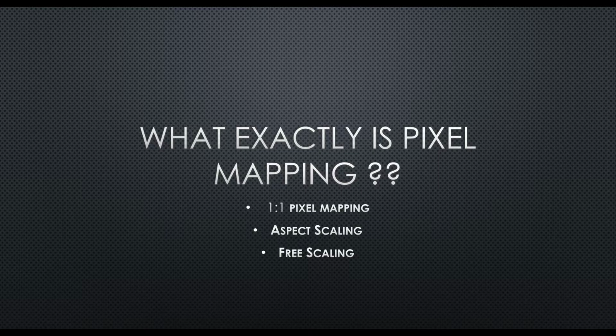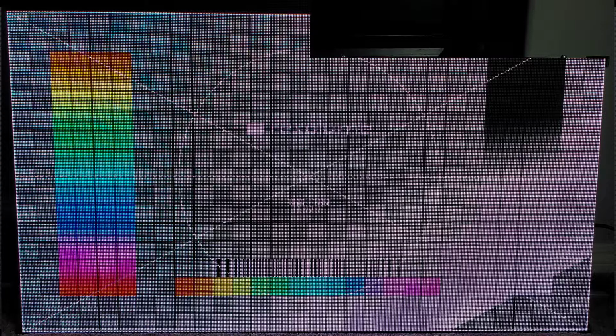Within scaling, there's aspect scaling and free scaling. Aspect scaling is basically scaling while maintaining your aspect ratio. If your signal coming in is 1920 by 1080, it is a 16 by 9 aspect ratio. If your LED screen is not a 16 by 9 aspect ratio screen, then you're going to have to do free scaling, in which case you're going to manipulate the image, and it's probably not going to look good because it's going to be squeezed. You might make some faces stretched out, you might make them squeezed in. While in aspect scaling, you will keep the aspect ratio and just scale it up or down to fit your LED screen.